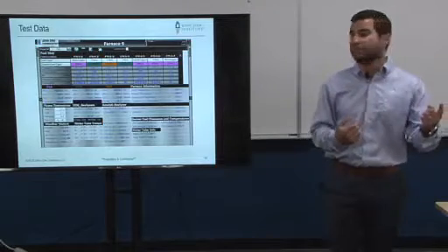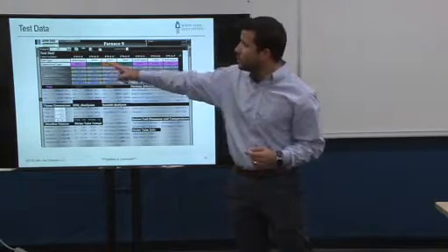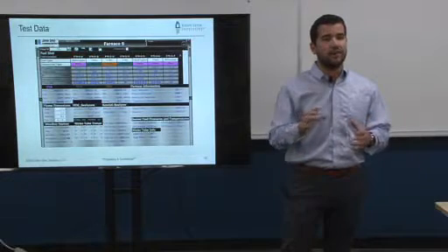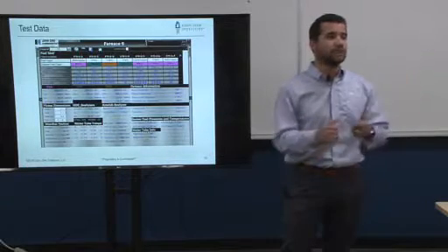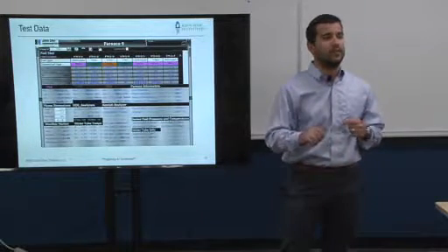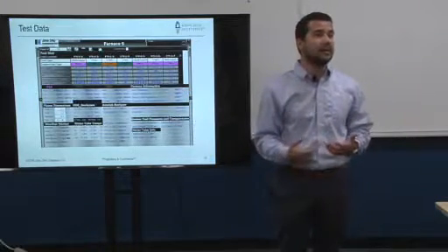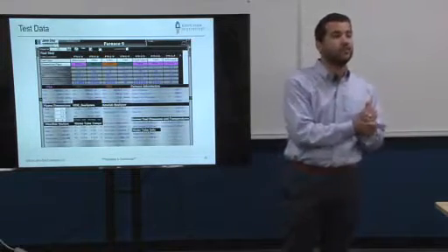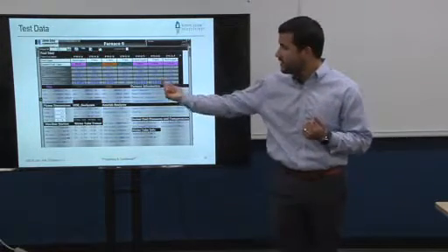Okay. But that really brings up a good point in the fuel line. You guys see the upper part of your screen here, you have all the different fuel lines that I have available in that furnace. What I have my operator do is open the valve to each. I can tailor-make which fuel, whether it's hydrogen, nitrogen, propane, goes to each of the lanes, and then I have him open the lane to a percentage to make a fuel blend that I design. And then that gets into a header or a manifold, and from that manifold it gets fed to the individual burner.